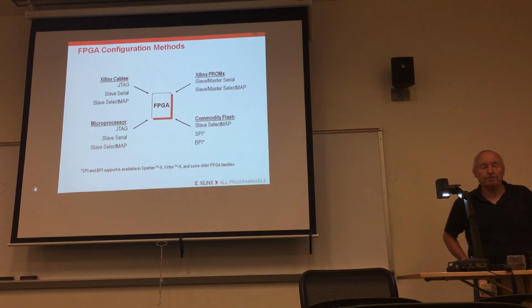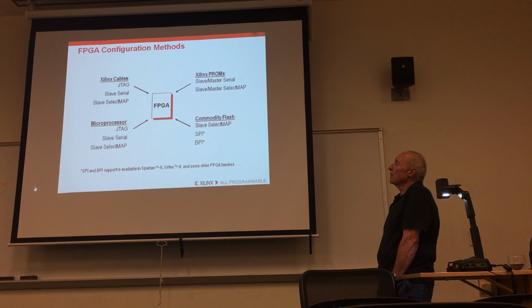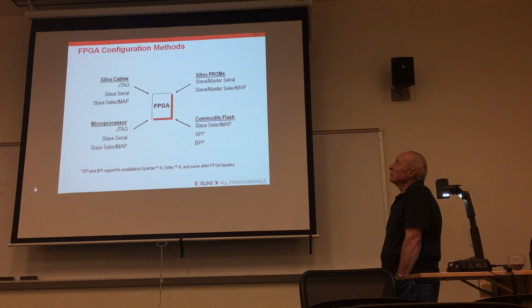These configuration schemes involve some other external control logic being used to control the configuration process. In these configuration modes, the FPGA is a slave to whatever control logic is managing the configuration. These configuration schemes require extra components and thus have added cost associated with them. Most users consider this configuration scheme if they already have the external control logic available as part of their system.